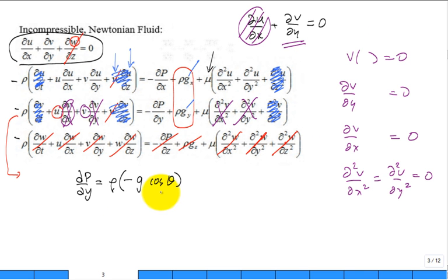And you could say, well, what about the pressure at some location, either at y equal to 0 or pressure at y equal to h? I'm going to spend a little time here beating the issues. There's not much here to get, but I'm just playing a little bit. So let's use this equation, which says that it's atmospheric pressure at y equal to h, at the outer edge of the fluid. And then I have this differential equation. You can solve for the pressure as a function of y.